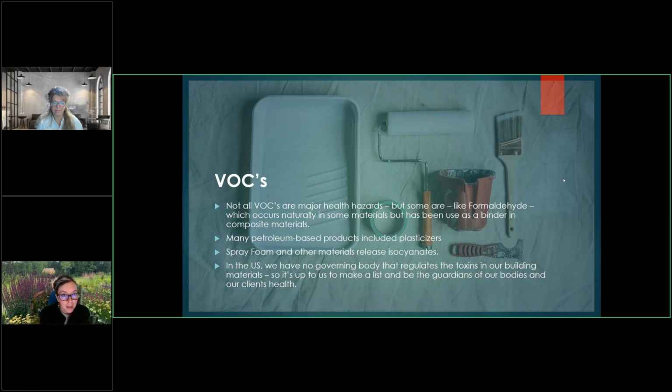Spray foams, if you've got to wear a hazmat suit to install it, you want to think about what it's made of and how well it's chemically mixed and its chances of continuing to off-gas. And in the US, just because we don't have anything that regulates that, it's up to us to make a list internally as part of your practice to be the guardians of our bodies and our clients' health.